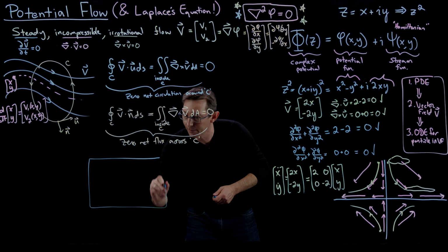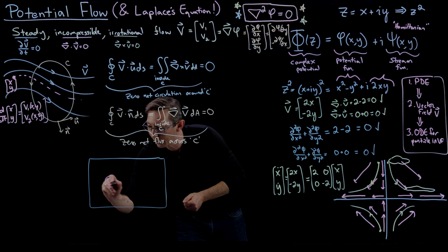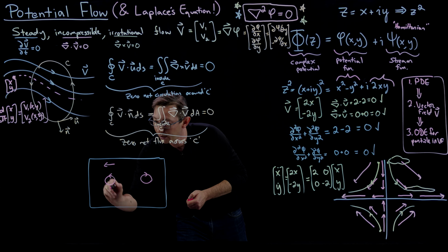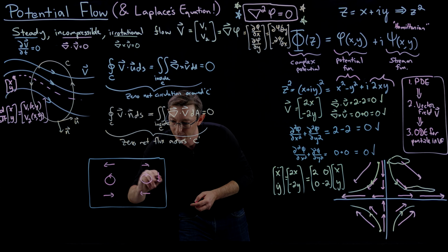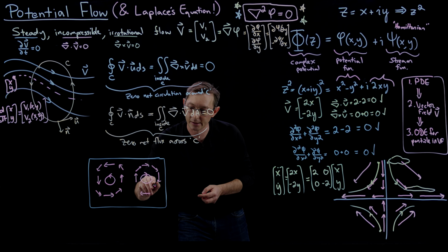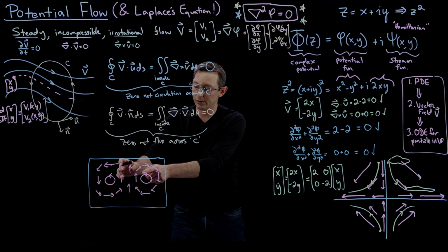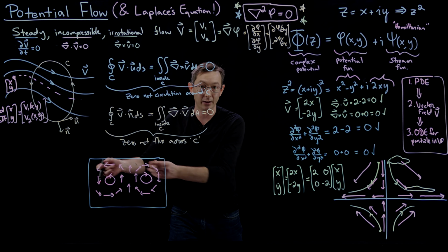So I can essentially build a potential flow in a box that has these two big counter-rotating vortices. So this one moves in this direction, this one moves in this direction. I hope I can draw this. It's a little tricky to get just right. Okay, this one's going this way, I guess this one's going this way, and so on and so forth. Okay, so this is just a big counter-rotating set of vortices. And it turns out that there is an approximate potential flow solution that gives you this kind of counter-rotating ocean gyre. And you can modify it to make these slosh back and forth.